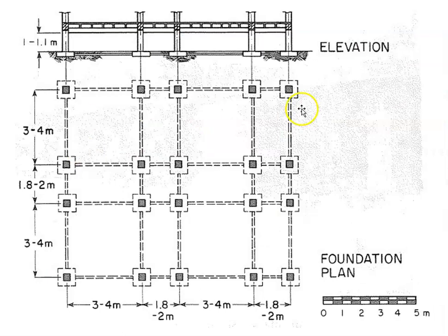And so here's a nice clear plan. So here we have some square pad footings, isolated footings, and then it looks like the dashed line here could be a beam, perhaps, connecting the two under the earth down near the footing. I see something down there. And then we cut through at our columns. So our columns are dark, and the footings down below are all dashed.